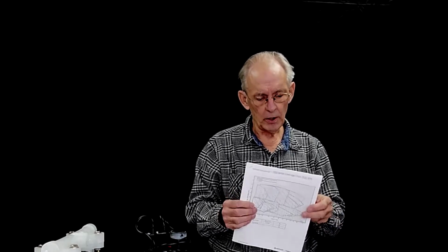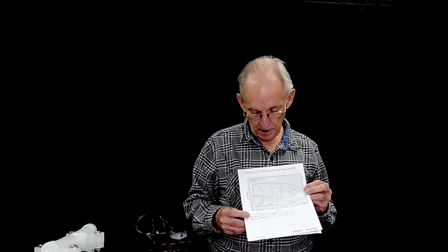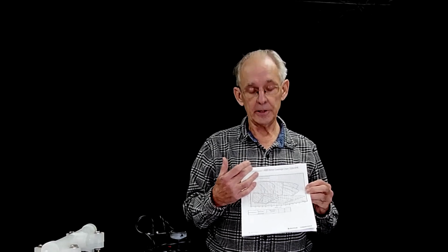And so this is just a chart showing one pump company's range of pumps, all of one particular design. And these areas that are shown are for different pump housings combined with different pump rotors. So a centrifugal pump, they aren't just built one way. They're built as you select the housing, and the housing typically gives you choices on what kind of ports they have, whether they're flanged or threaded or hose ports and so forth.